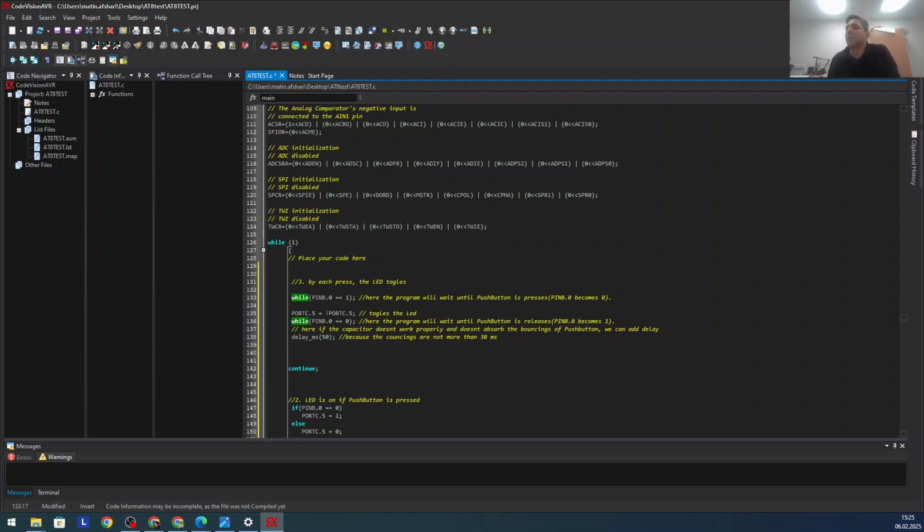It means while pin B equals 1, it is pulled up. You remember, if it equals 1, it means it's not pressed. And so we say to the microcontroller, until the push button on pin B0 is pressed, stay here, don't go forward. So the program pointer comes here, reads this, and sees this. Yeah, it's not pressed, so I stay here. I will not go forward anymore.